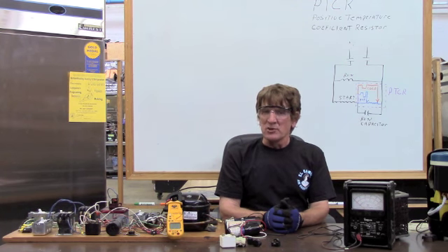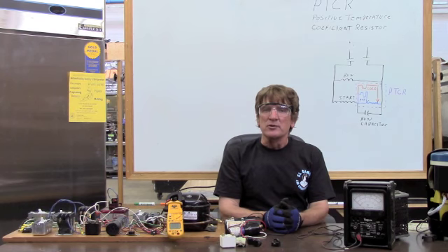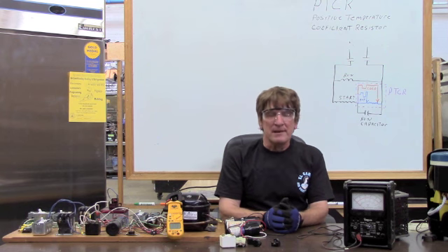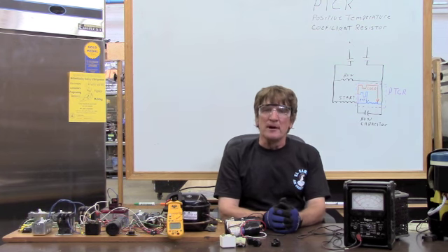As resistance goes up, current will go down, reducing the amount of available torque to a start winding. So as that PTC warms up, it's going to allow less current to flow to that start circuit and will basically de-energize that start circuit when the compressor is up and running. If I take a look at my pictorial behind me,